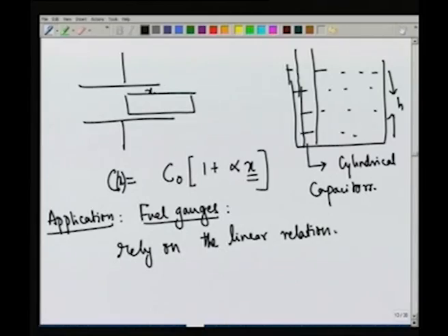So if you go up and open up your fuel tank and look for where the capacitor is, these are, as I told you, long capacitors but with very little spacing. Of course, modern day fuel tanks may use something more sophisticated. The spacing between them will be of the order of a millimeter or a fraction or so. Therefore, that is how you build a fuel gauge in order to measure the height of the tank. It exploits the dielectric property of the petrol. By the way, petrol has a dielectric constant of something like, I think, about 2, therefore this works quite well.